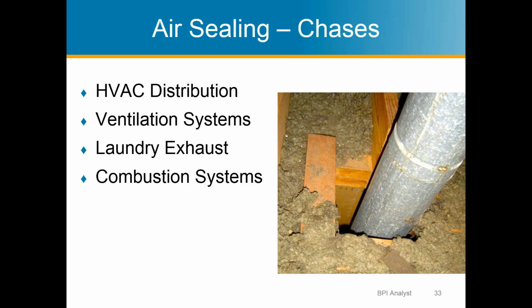Hot air rises. Well, now, as you can see in there, of course, nobody insulated that wall inside the chase. And of course, you need six sides. So that chase that runs straight through the house is a wall that's usually right in the middle of the house that has absolutely no insulation in it. Can't really do much about it at this point when you find it like this, but what you can do is put a cover at the top of this.